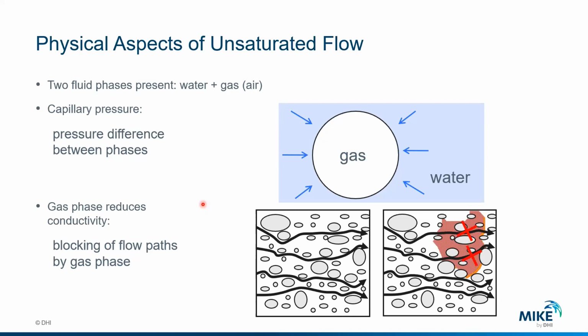So FEFLOW is one single phase. We talk about gas, we talk about water, we talk about unsaturated porous media, which is gas, the rest, but we're still working in one single phase. So why do we care about this? Because if we have saturated media, it makes a difference compared to unsaturated media, because in the unsaturated field we might have this connection of different flow fields, because maybe the porous media is partially unsaturated.